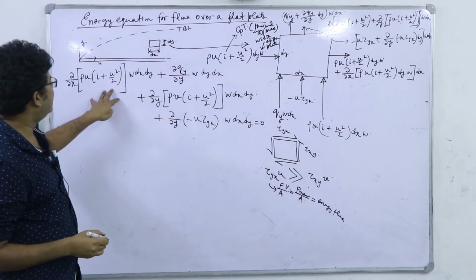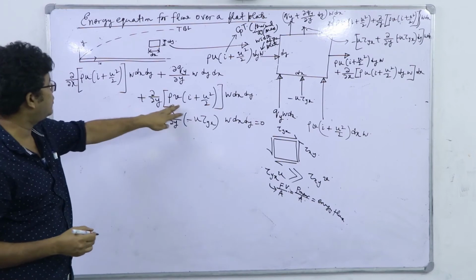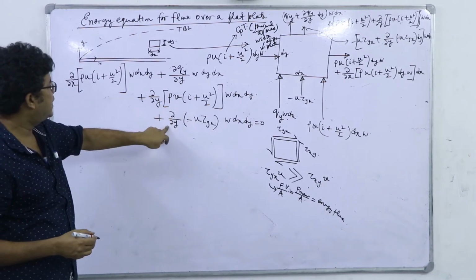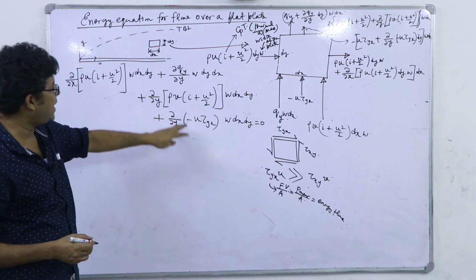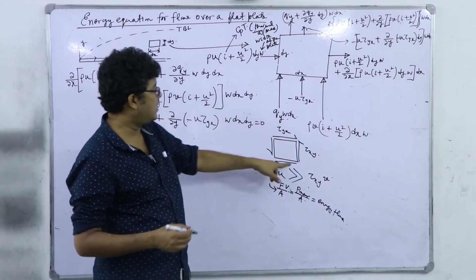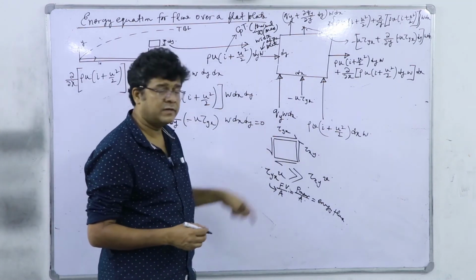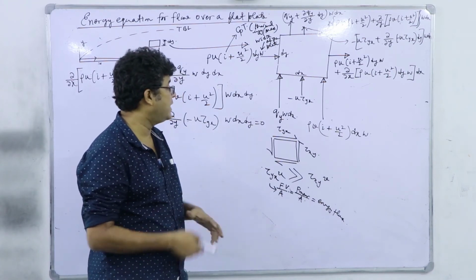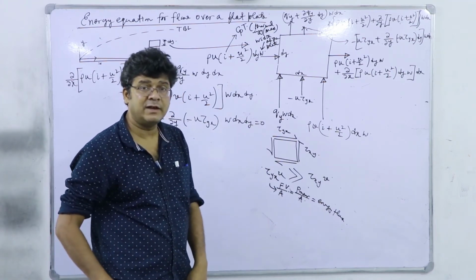So overall we have the x directional total energy transport, the y directional transport, the y directional conduction of heat, and the x directional viscous dissipation. It is referred to as x directional viscous dissipation because the force direction of the respective shear stress is the x direction, and that is why in the assumption we mentioned that we are neglecting the viscous dissipation in the y direction.